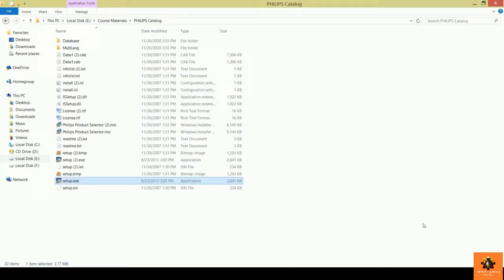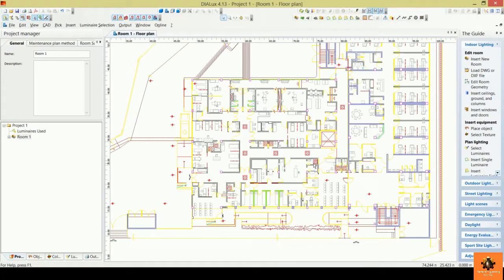And then I'll go back to the DiaLUX software, and at that point the next step we need is to explore the CAD layout we have. This is because if we need to make a correct lighting system design, we should understand the design that we are working on very well. So we should know the type of each room, as according to the room type we specify the amount of lux that this room needs. So let's explore the hospital layout we have.